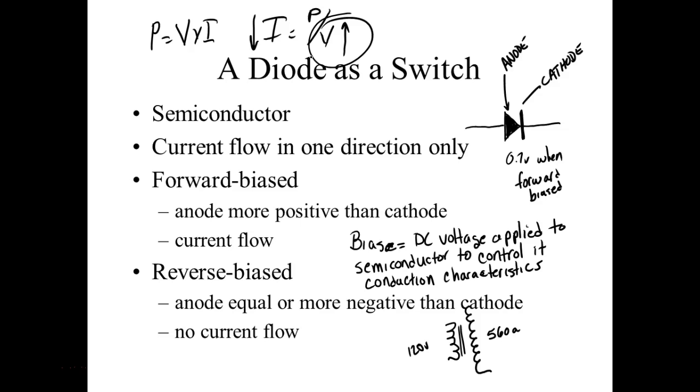So the advantage, and AC induces a voltage. So that means I can have a motor where, instead of having a connection to the rotor, I can induce the voltage into it. All electric motors work off the repulsion and attraction of magnetic fields. Well, I can induce a voltage on an AC motor. I can induce a voltage into the rotor, which generates a current. And if I can make one of those fields move, the motor runs.